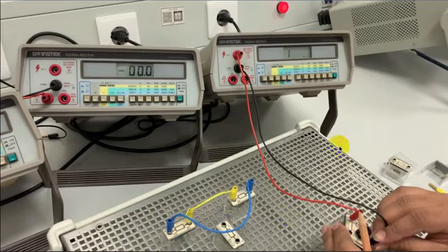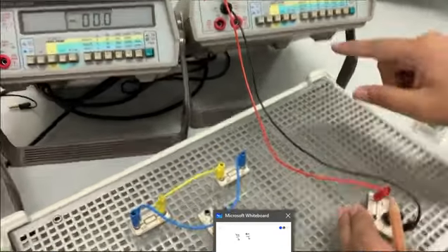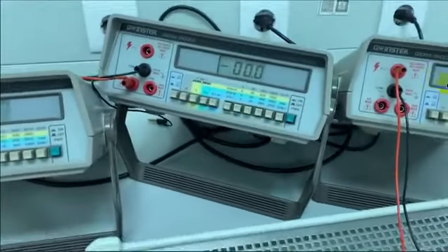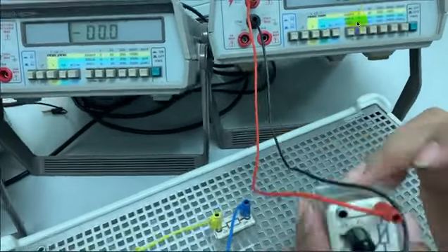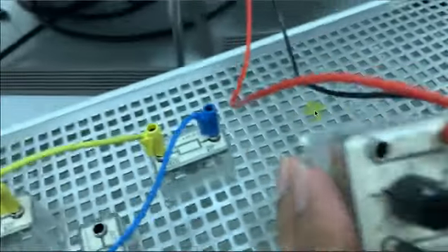Okay. I will take the 470 potentiometer, a potentiometer with the value of 470, and I will set the value of R Thevenin by using the potentiometer. Next, now just connect it crossway. Just vary from here. Vary the knob. Vary the knob.